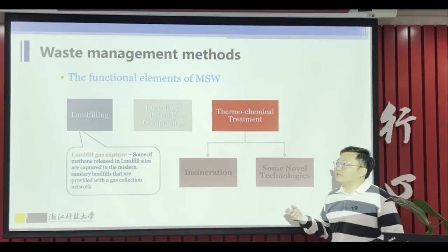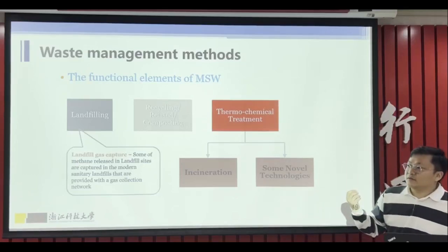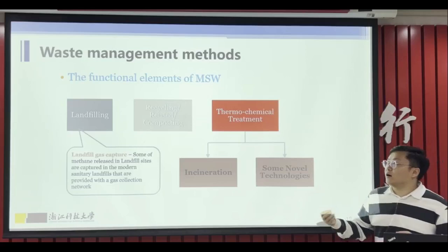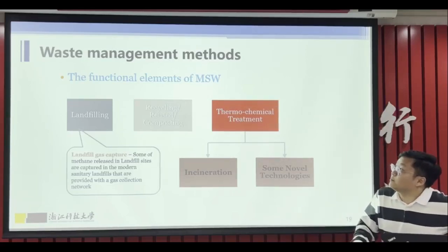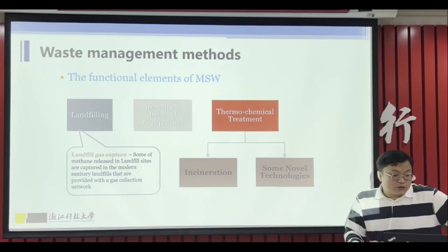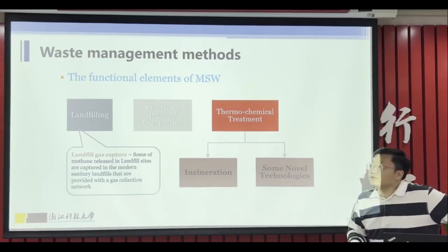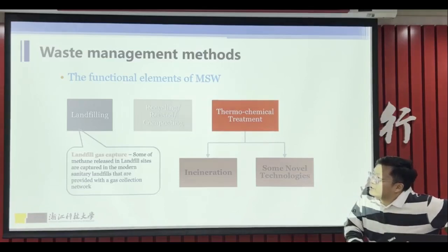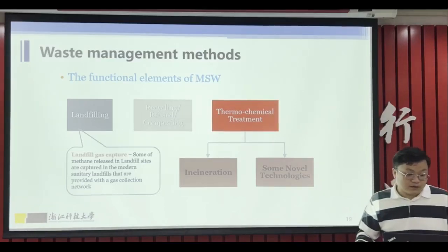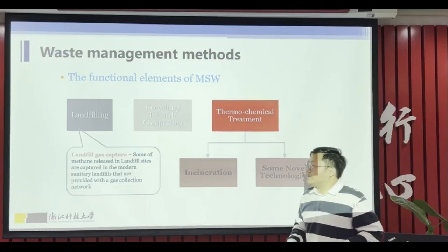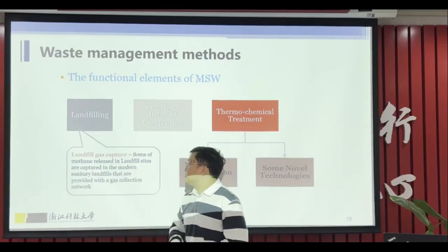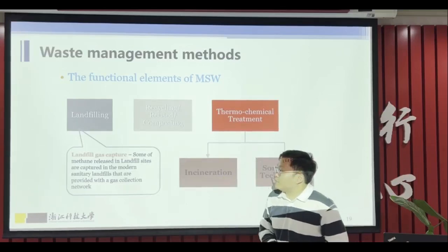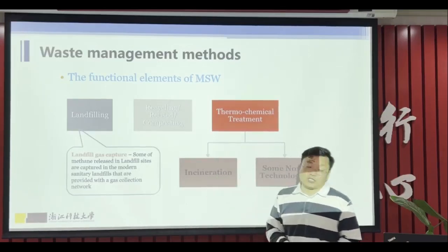Open dumping is an uncontrolled method, and landfilling is a controlled method of municipal solid waste disposal. And also, when we do landfilling, we should capture the landfill gas, which is mainly methane released in landfill sites, and should be captured in modern landfills that are provided with a gas collection network.